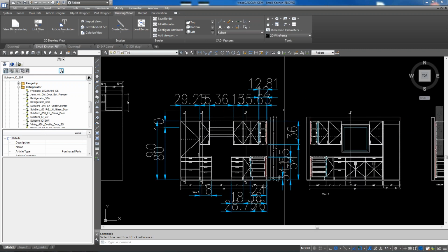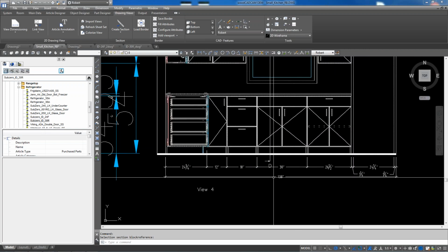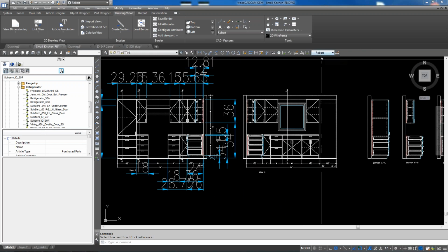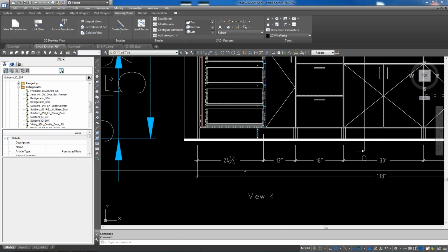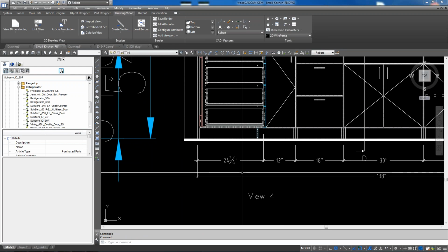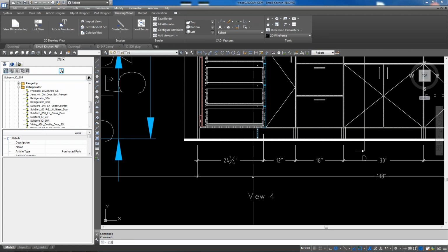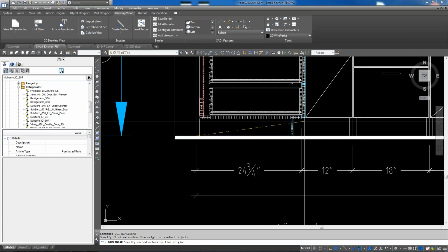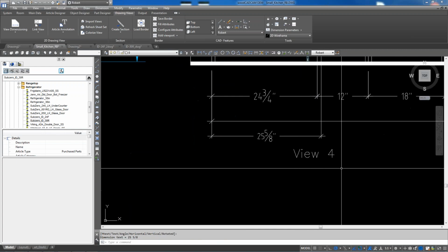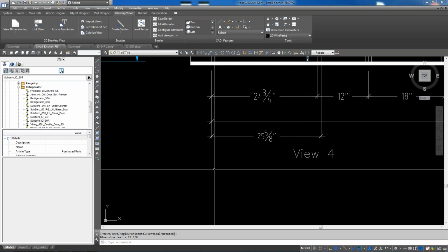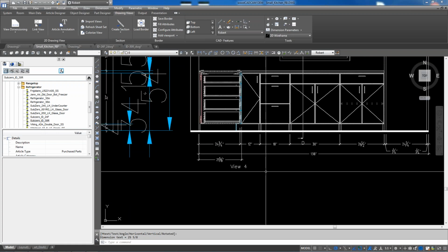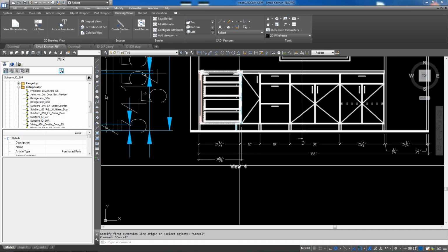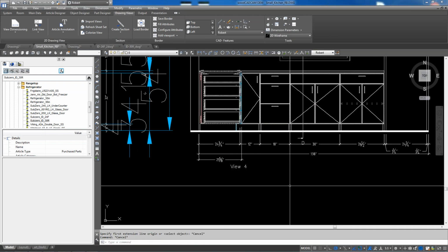Okay then, so regardless of auto dimensioning, I tried to dimension manually, and I modified a little bit of one of the setups. I created my own, and then when I dimensioned something, it didn't give me the same look of my dimensions. It was usually bigger numbers. Let's say if I try to dimension this again. Of course, now it works. I wonder if maybe that scaling that we turned off has something to do with it. Yeah, I think it does.